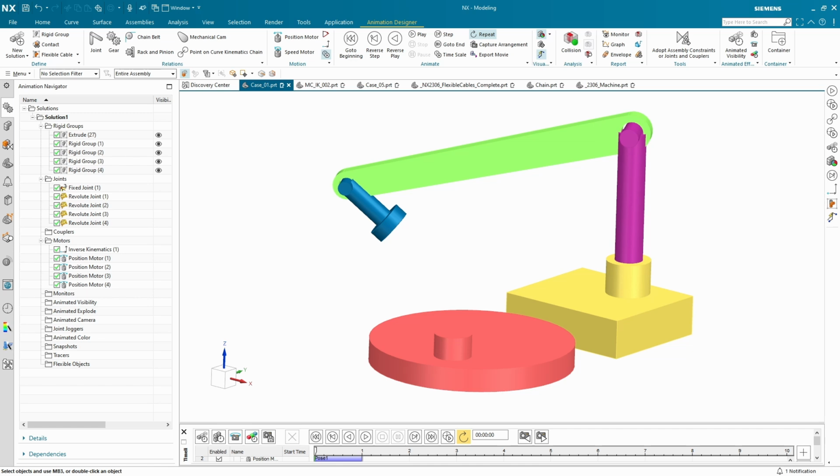Technically, there are two solutions here. That platter could be in two different locations, but there's a very limited number of solutions. In this case, inverse kinematics will solve the nearest solution, and that's what it will return. Keep that in mind. If your system has an infinite number of solutions, inverse kinematics won't work.